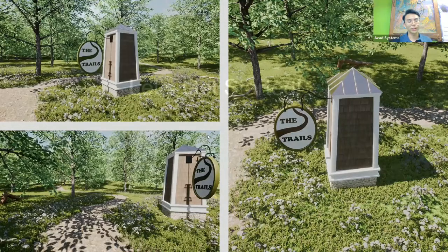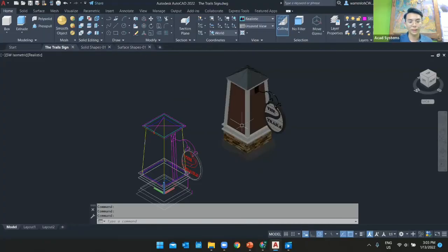So let's get started. We will go to the AutoCAD software. And okay, so here is my AutoCAD 2D software. Once you are logging into this software, you need to change it into 3D modeling. Every time you use AutoCAD, if you are using 2D, you need to change it by clicking the setting button below here. Click it, and you can change to 3D modeling. Usually, the default setting will be drafting and annotation. So you need to click on 3D modeling to change it to this tab. You have the home tab, solid tab, and this surface tab in 3D.